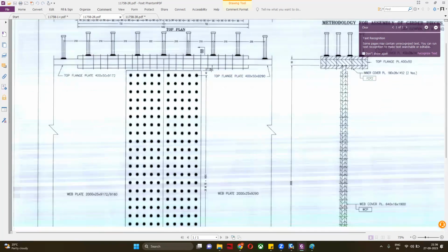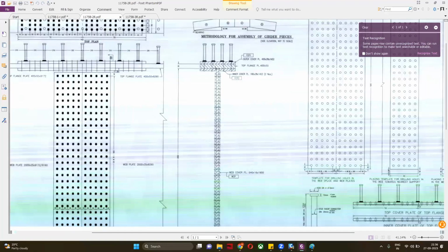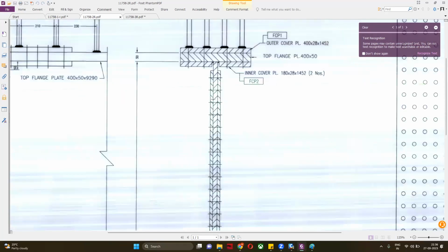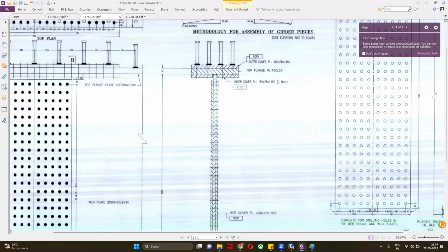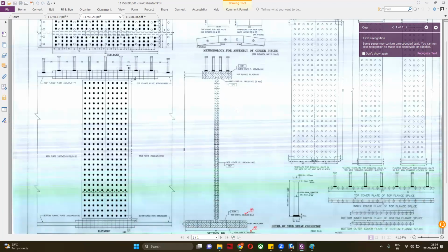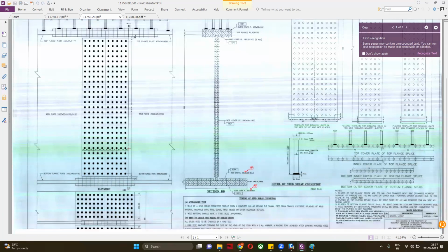So this connection thing is a different kind of thing. You can see web will look like this: one plate here, and this in the middle. Cover plate, inner cover plate and outer cover plate, something like that. Yes. Cover plate or normally connection plate, splices plate. Its naming can be different according to the local naming changes. For web also, one more plate they will be putting. Even if you do not see any backing plate, backing plate is also used, very common in connection, but not required in this.